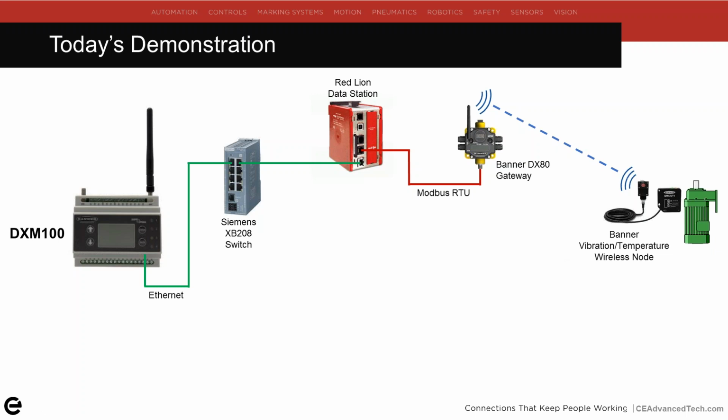It's going to hop from frequency to frequency. Node 1 may be at 907 megahertz this time around, and the next poll I'm at 912. That seems random, but it's a pattern built in and exchanged between the two devices when they're first linked. So that random hop table is what gives us that security, plus the fact that we have a proprietary packet out on the wireless. So you certainly wouldn't see it with any normal wireless device to begin with.